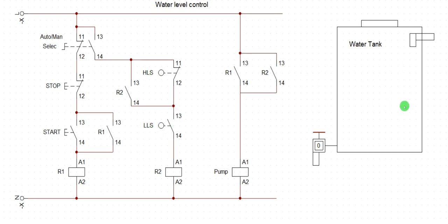I will have them installed right inside the tank. Let me see if I can have a sample of them and put them here, at least for a more elementary understanding. So look at this and look at this again. This low level switch, this high level switch. This one is responsible for cutting off the water from pumping when you get to a certain preset level. Then this one is responsible for cutting it down when the water has discharged up to this particular level.